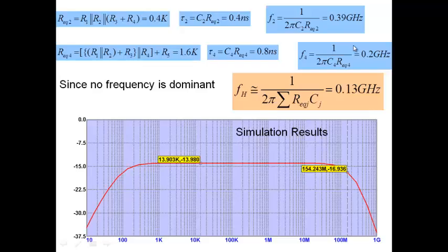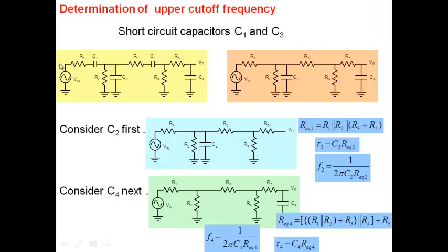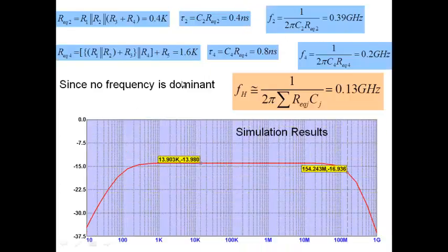We are discussing, all this discussion is in a specific context of amplifiers. In amplifiers, we said that all those capacitors that you see here are all in microfarads. The transistor capacitances are all in picofarads. So yes, in general it can happen, if I had an arbitrary choice of capacitors. If I put these capacitors in picofarads and these capacitors in microfarads, yes, those kinds of things happen, but not for amplifiers. Okay, so that's the procedure then.